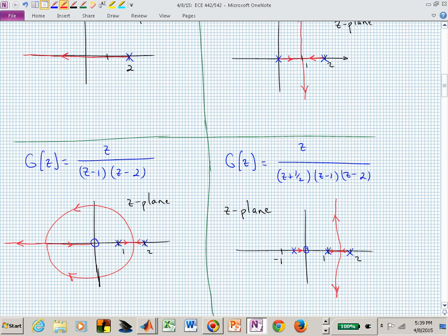What's the pole zero excess? How many root locus branches do we have? We haven't really talked about that, but how many poles do we have? Open loop poles. How many closed loop poles do we have? Same number. We had 2 open loop poles, we have 2 closed loop poles, we have 2 branches of the root locus. They're going to start approaching each other.